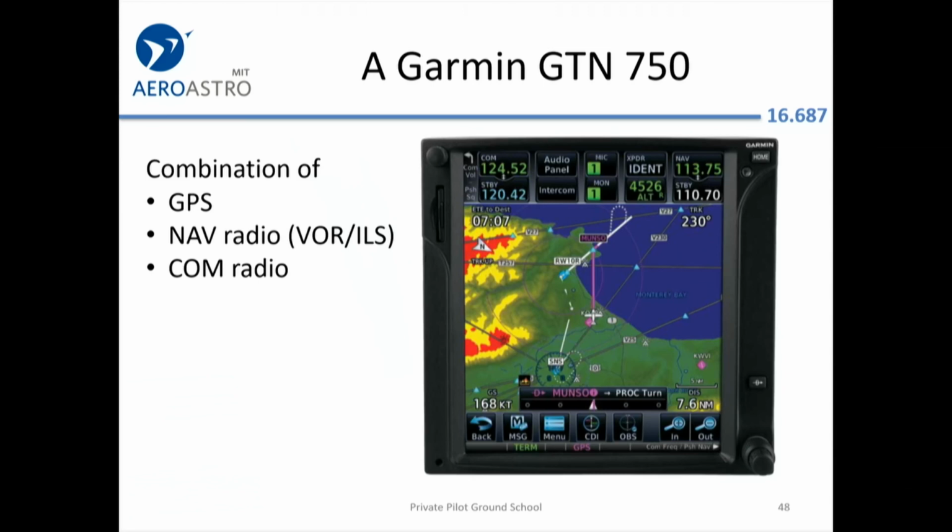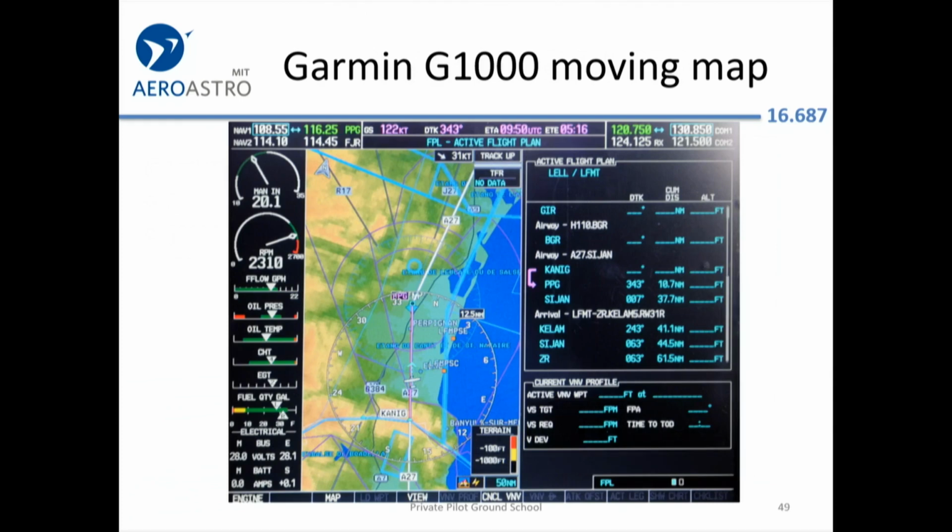And I think they actually have 3 separate power supplies. So there's a connection to the box, maybe for power. But after that, you can have a tremendous amount of failure inside the box and still have a subset of the functions working. I guess if the screen fails, you're kind of out of luck, which is why every IFR certified airplane that I know of that's newish has a second one of these, usually smaller, a Garmin 650, which is physically smaller.